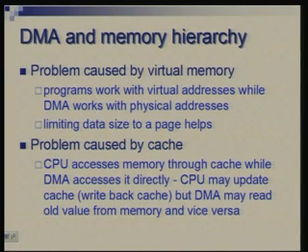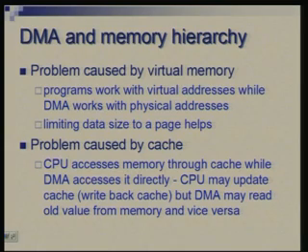What it may mean is that you would need to do translation of the address. So, when you are initiating a DMA, you would need to specify a physical address for the DMA controller. You need to tell the DMA controller to transfer, let us say, 8K bytes of data to this physical address, and the program would be working in terms of virtual addresses. So, if you have created an array, you know its virtual address. So, there has to be an explicit conversion of that virtual address to get to the physical address.